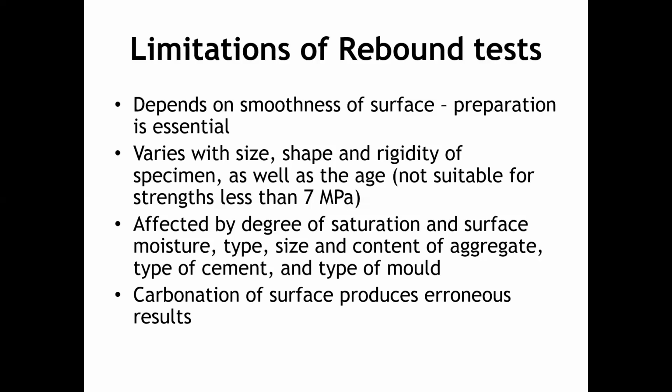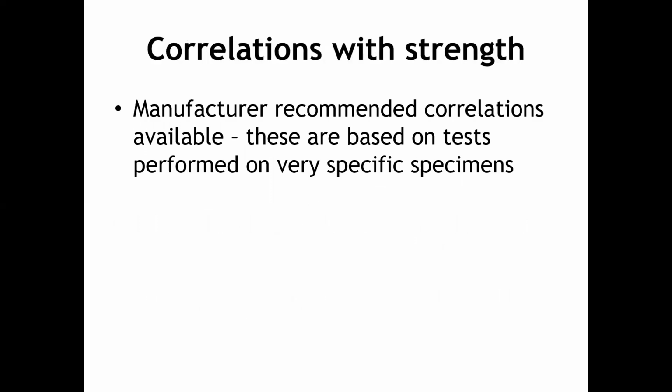Once it gets reduced, the concrete becomes harder. When it becomes harder, when you hit it, you get a very high rebound number from this rebound hammer test, but that may not be a correct indicating number of this cover concrete. The increased number would have been because of the carbonation taking place.